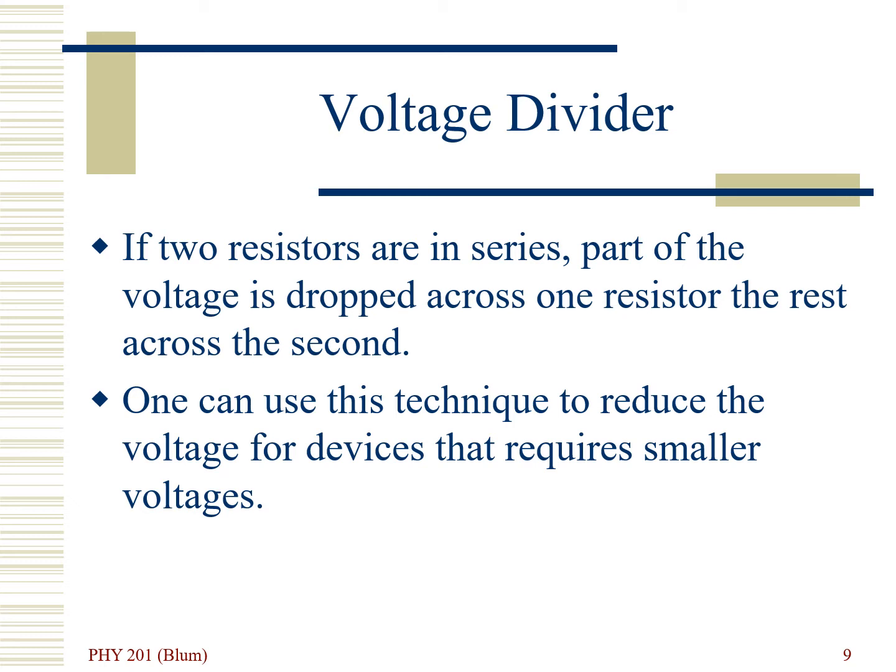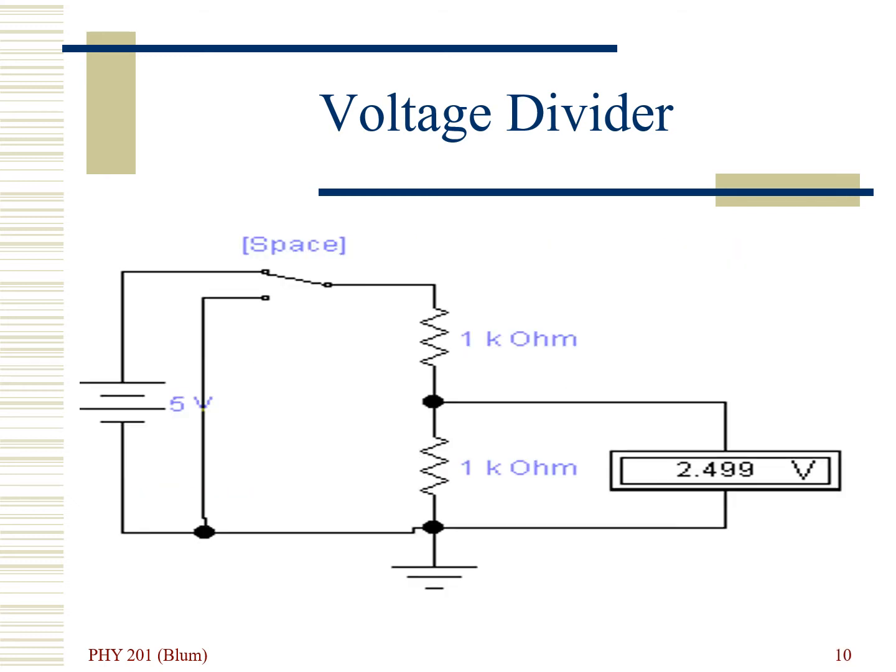We're going to have two resistors in series. So part of the voltage will be dropped across one, the rest will be dropped across the other. So then if we take the voltage at the point between the resistors, it is going to be some fraction of the overall voltage. So somewhere between the high and the low, an intermediate value. So the circuit here can be called a voltage divider. It can also be called a 1-bit digital to analog converter.